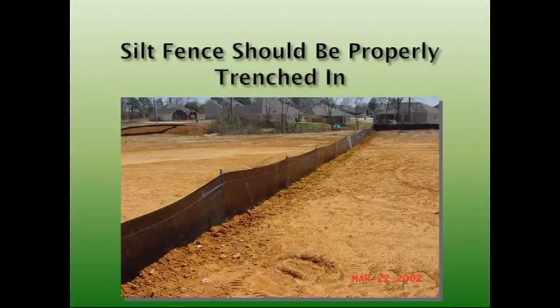There's really no reinforcement there. If you see this one's kind of got the trenching effect down here, you probably want to compact that a little bit more just to make sure it's compacted. They're going to show you an example out here. We got some people to install some silt fences for you to show you exactly how they need to be installed. But just make sure they're trenched in.